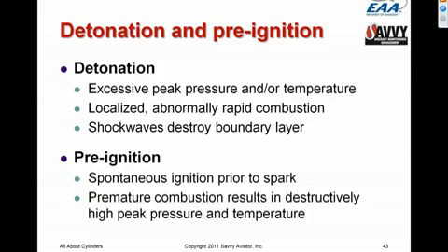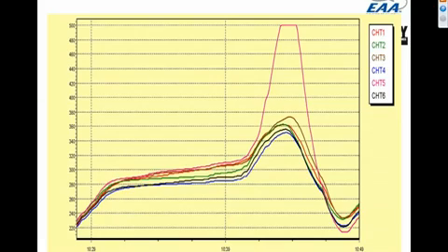Let me show you very quickly a couple of preignition events, destructive preignition events that we have engine monitor data to capture. This one is out of the Cirrus SR20. It's almost a brand new Cirrus SR20. It happened to be in the UK, and the pilot applies full power for takeoff. We're looking at cylinder head temperatures here. 5 of the 6 cylinder head temperatures come up normally, up to something like 360 degrees Fahrenheit, which is typically where they ought to be at takeoff power.